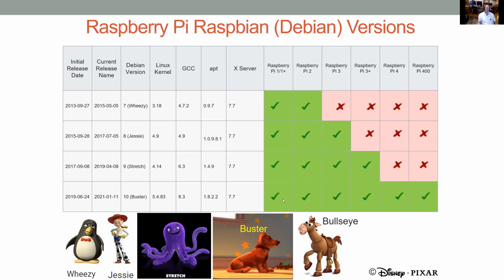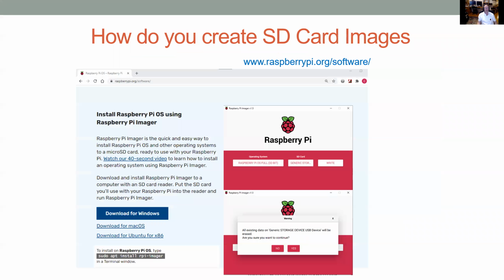So if you do something on a Raspberry Pi 400, it actually still works on the older Pi. So your SD card is transportable to a point, as long as it's not an SDXC, which isn't compatible with the Pi 2s, and I think also the Zeros. That's the only caveat, the actual SD card, but the code is compatible, which makes it very nice.